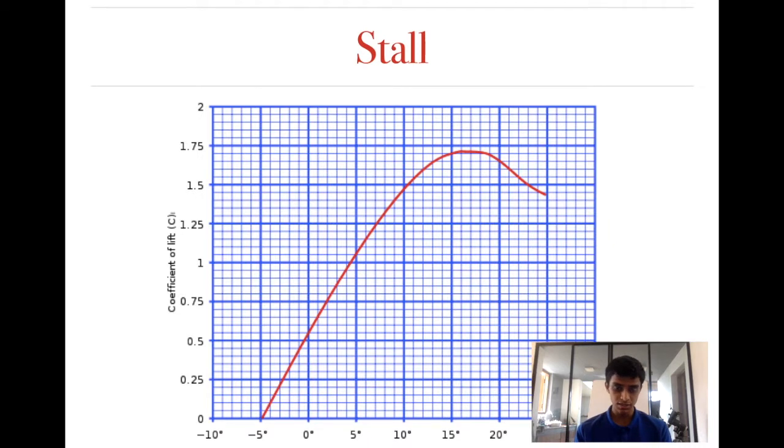Right, okay, with this, you can see that when the angle of attack is 0, you have a coefficient of lift of around 0.6, I suppose. A bit more than 0.5, sorry. And when the angle of attack continuously increases, the coefficient of lift increases, and we have a maximum coefficient of lift at an angle of around 17, I suppose. Yes, around 17 degrees, you have a maximum coefficient of lift. But at 25 degrees, it's completely off. There's no lift, meaning the stall. So remember that I told you in the previous slide that a stall occurs at around 15 or 16 degrees, but this one is 25 degrees, right?